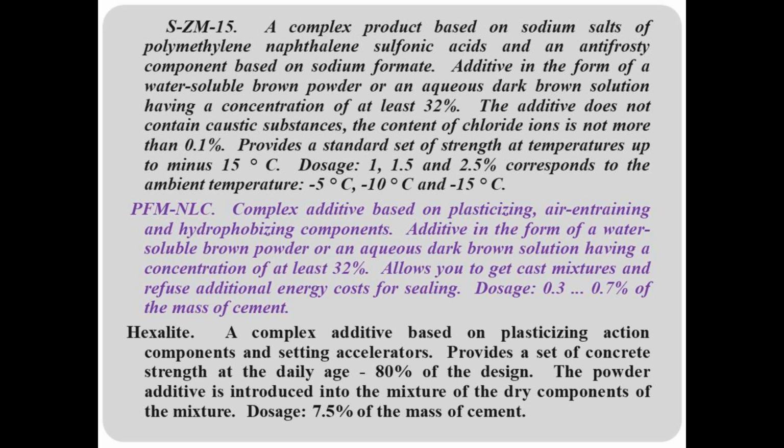PFMN, a complex additive based on plasticizing, air entraining and hydrophobizing components. Additive in the form of a water-soluble brown powder or an aqueous dark brown solution having a concentration of at least 32%.